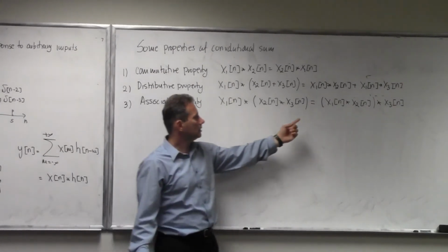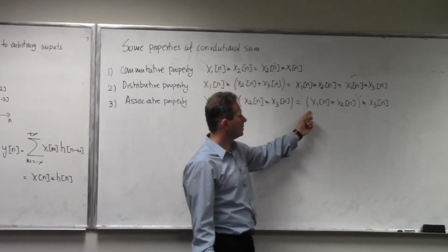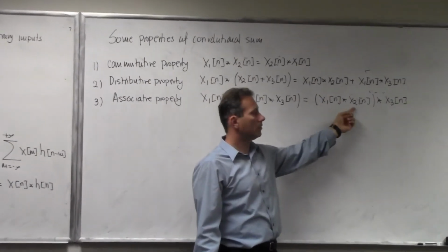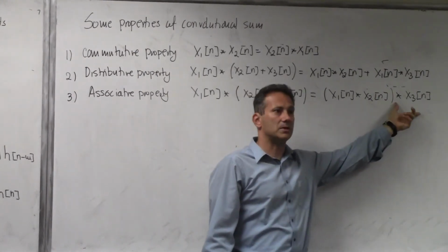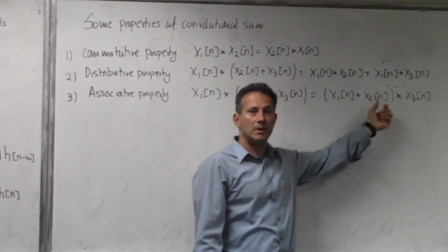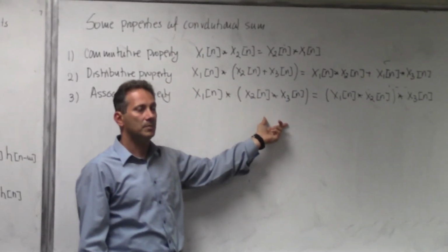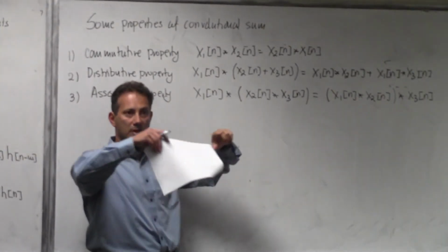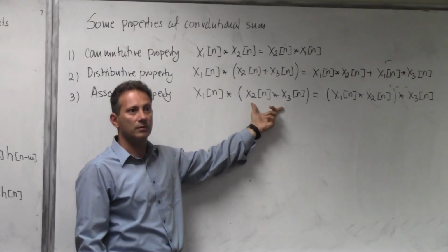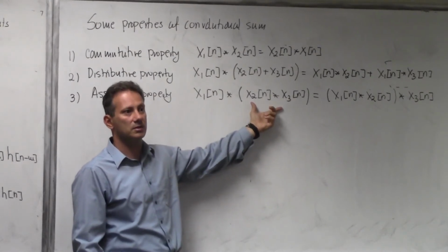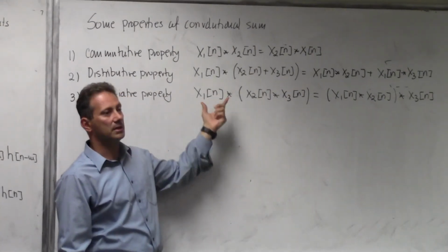To obtain the overall response, you would have to take the input convolved with the impulse response of the first one, and then convolve that with the impulse response of the second. Well, we can approach it differently. We can understand these two systems in cascade as one system, put in one box, whose impulse response is the convolution of the impulse responses of the individual ones. And then we can treat the whole thing as one system to which we present the input.